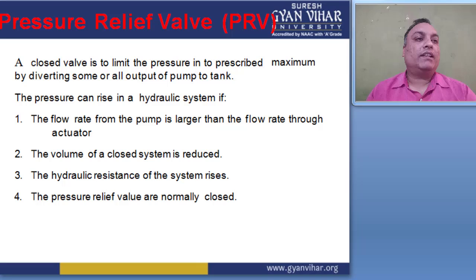points, and pressure can rise in a hydraulic system if the flow rate from the pump is larger than the flow rate through the actuator, or the volume of a closed system is reduced, or the hydraulic resistance of the system rises.